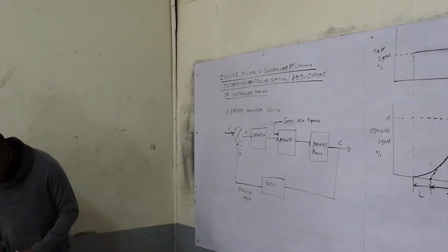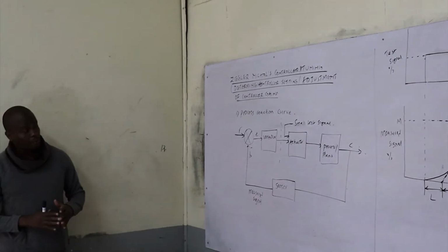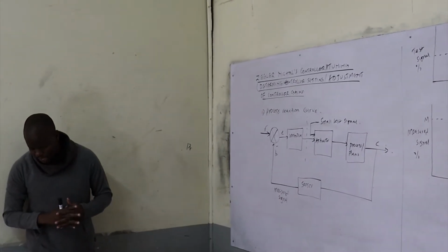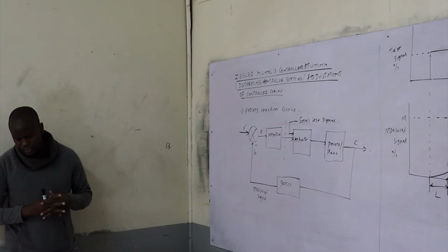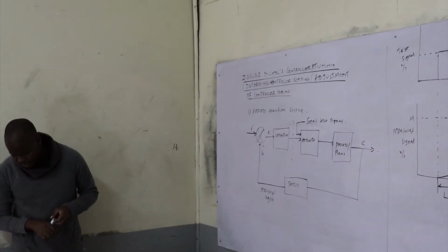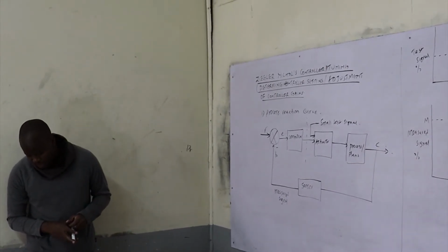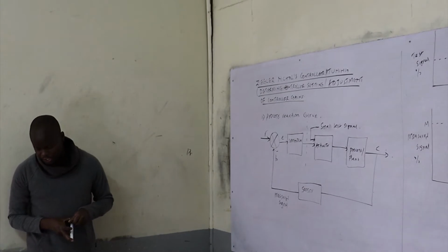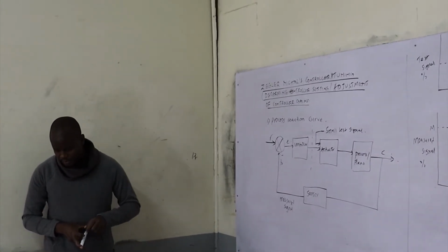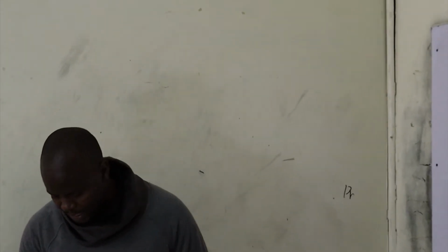So when we use this method, as we have said, the procedure is always to open the control loop so that no control action occurs. Generally, this is always made at the actuator, which at times we refer to as the correction unit. Then a response of the measured process variable will be determined.